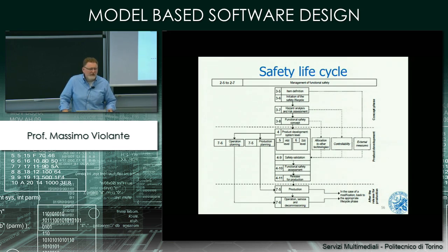This is a way of informing the driver that the ABS is not there to help him or her. This way, we hope that the driver will take the proper action to manage this scenario. Typically, he or she will reduce the speed and will not brake suddenly.